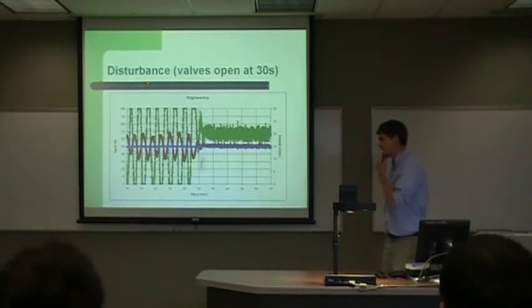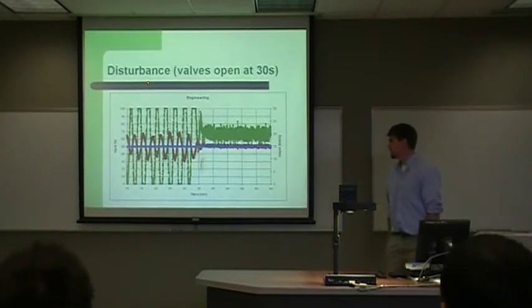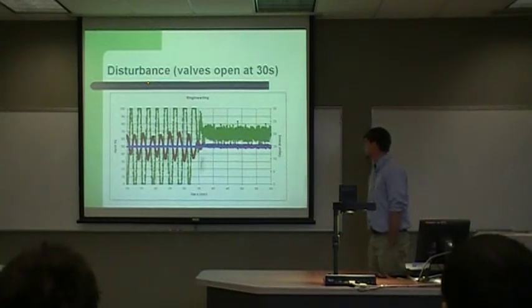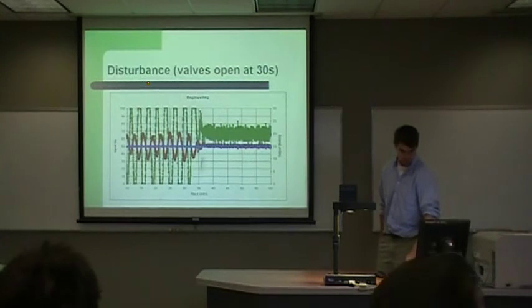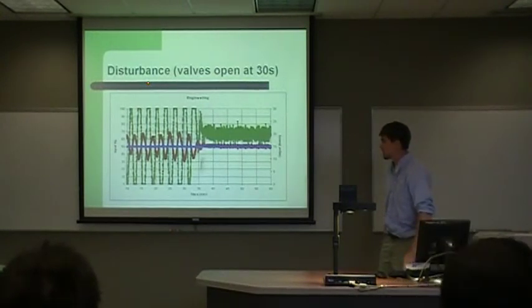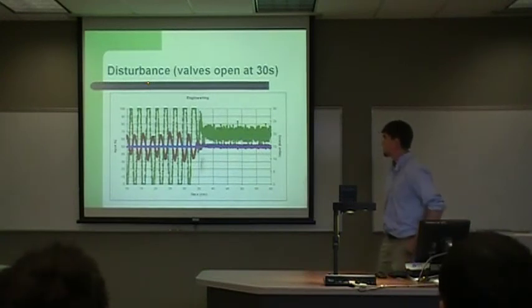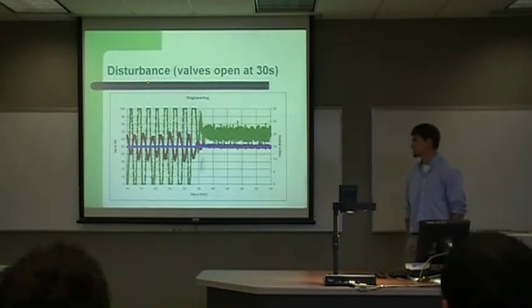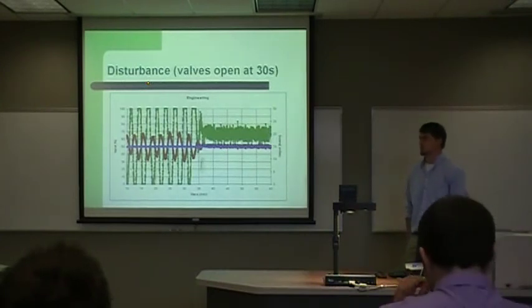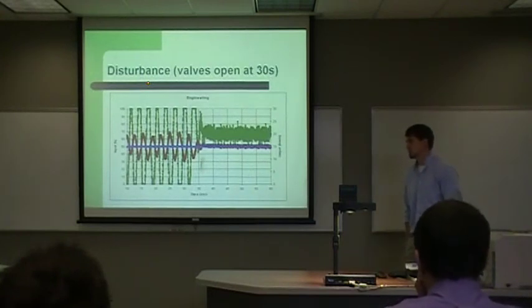Red tape is always valves open, right? Yeah, all valves open, which is the situation on the right-hand side of this graph, am I right? Yes. And the point we can see here is that if those valves get closed, the same PI controller that works fine when the valves are open goes bananas. So that's something to think about in how you choose your parameters, so that for a disturbance, bad things don't happen.